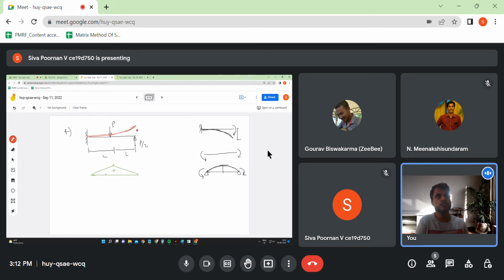Okay, so this is like a bow, like what you said last time, right? From this we can only know its shape, but not exact displacements and rotations. It can have a rigid body rotation in addition to the way a simply supported beam would deflect. Therefore, if you compare it with the simply supported deflection from the midpoint, it's just a rigid body rotation of that. Okay, so that is the deflected shape.